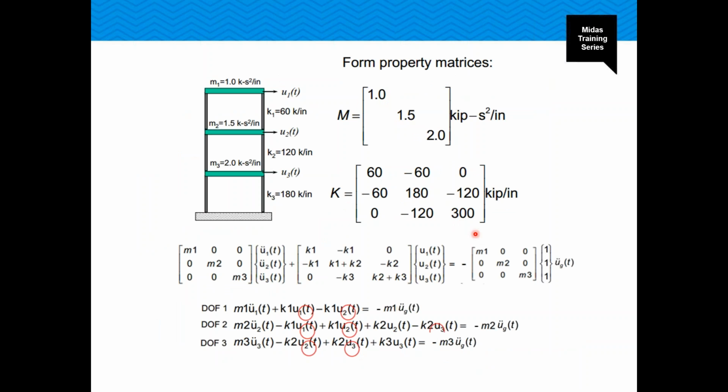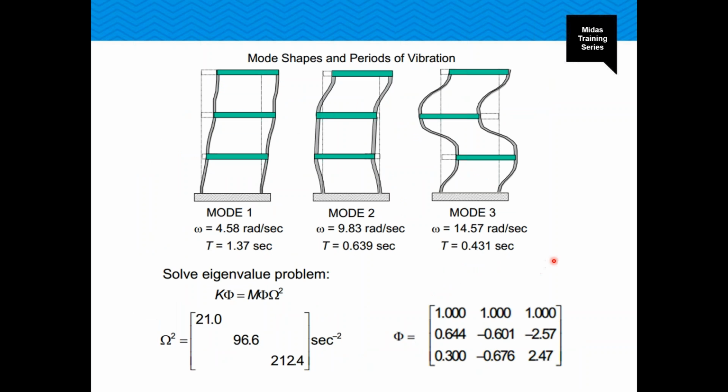If we apply dynamic equilibrium at the 3 different levels, the equations are coupled with each other. This building has 3 natural modes.